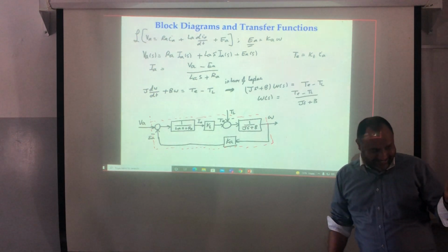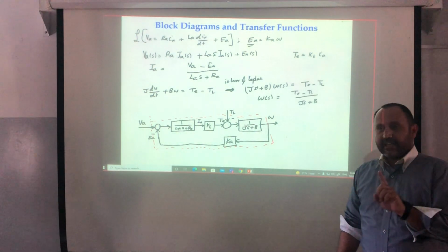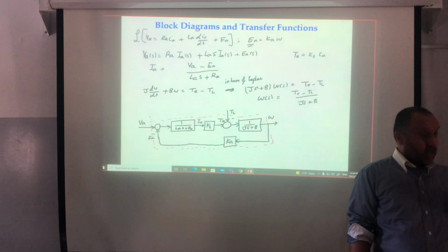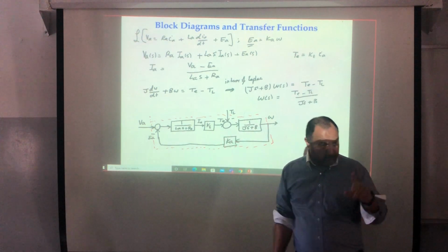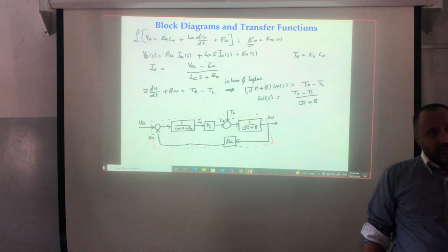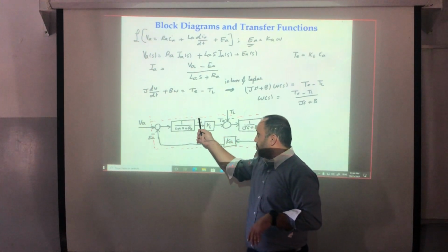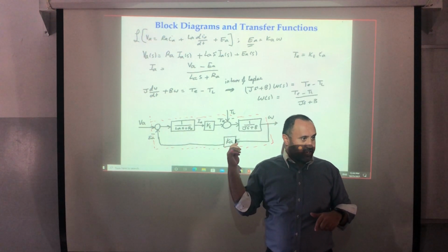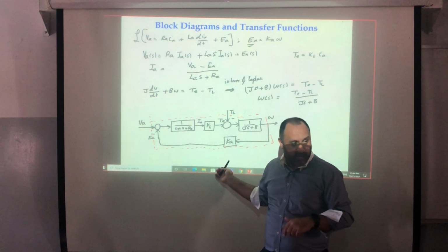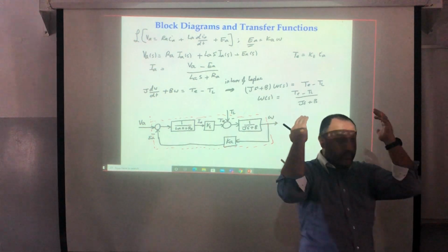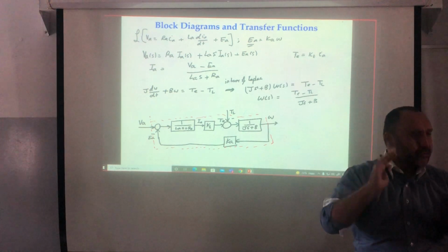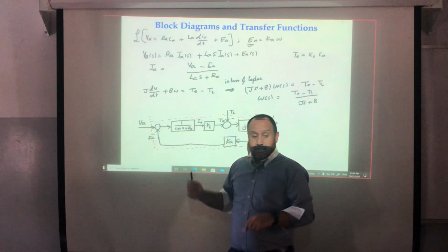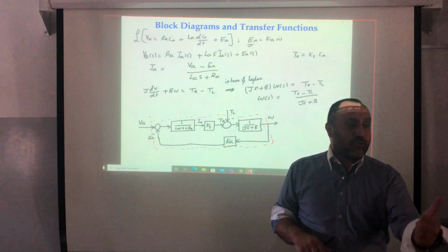He's a genius, by the way. Imagine that I'm using high gain in controlling the current. If I'm using high gain in controlling the current, then here I'm having what? K multiplied by the current, correct? Then you know that I can reshape the block diagram. If I need to put K here, I will divide by K, correct? So KT over the huge K is what? So this one will be 0. And simply this means that now the current inside the machine is equal to my reference.